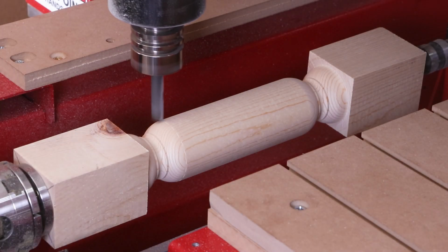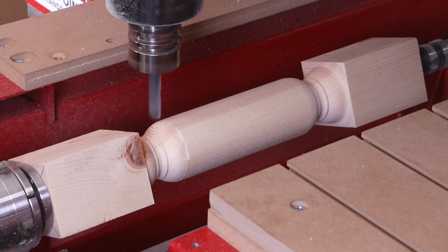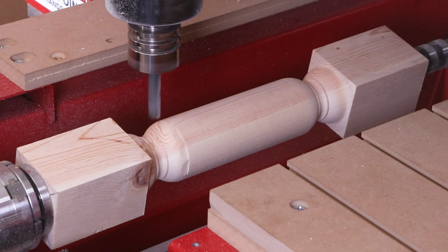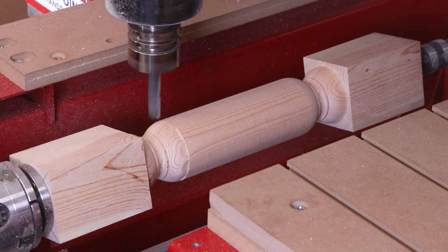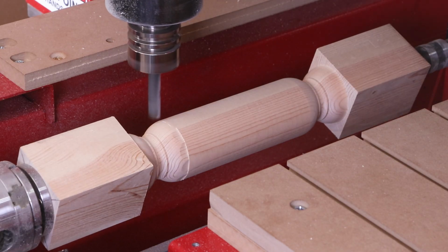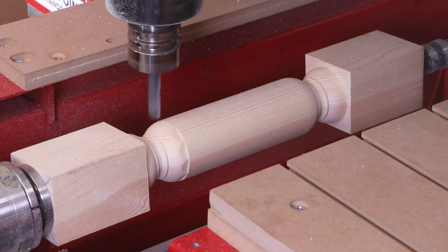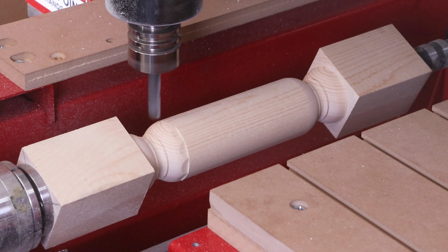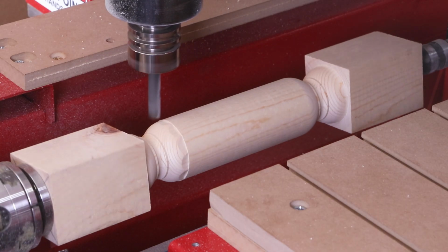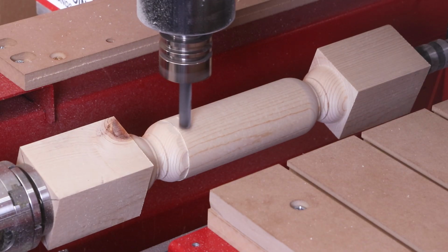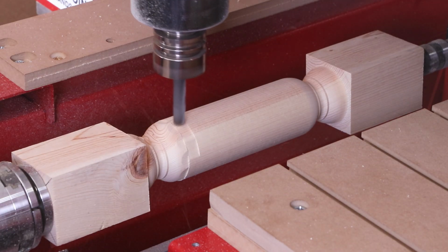So just like we programmed, the cutter comes down to the starting position directly off of the material and then travels across the part to machine its first flat section. The indexing process then takes place, and this whole thing repeats itself around the circumference of this part. Once that first section is complete, the cutter shifts over the width of the tool, and the material slightly indexes so that the brick pattern is placed 50% different from one section to the next.